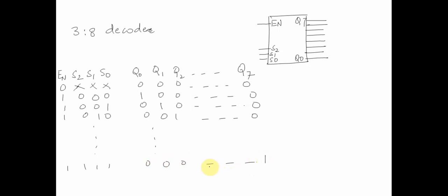This is a 3 to 8 decoder, and if you have to build this 3 to 8 decoder, we have to take enable into consideration, and then look at each and every combination, right? Q0 would be equal to enable dot S2 bar S1 bar S0 bar, right? And similarly, in each expression of this decoder one term would be activated. Q0 would be activated for one set of terms, Q1 would be activated for another set of terms, and Q3 will be activated for another set of terms.